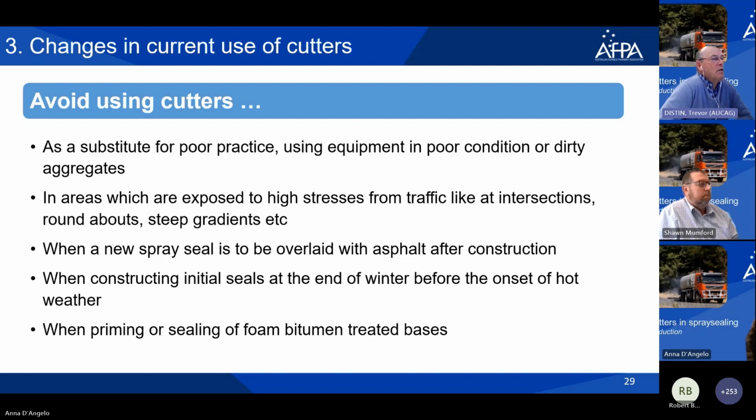And also important is timing. If you're constructing a new seal at the end of winter, if you're going to put cutter in there, the risk is that you'll still have trapped cutter in that binder, and with the first hot weather you're going to have potential bleeding, because it can take up to 3 months as a rule of thumb for 80% of that cutter to escape out of that binder.